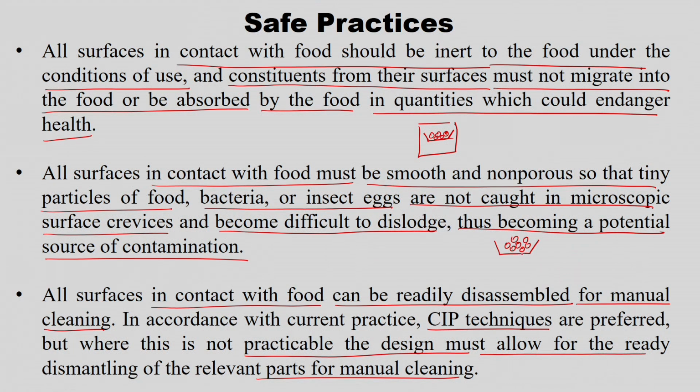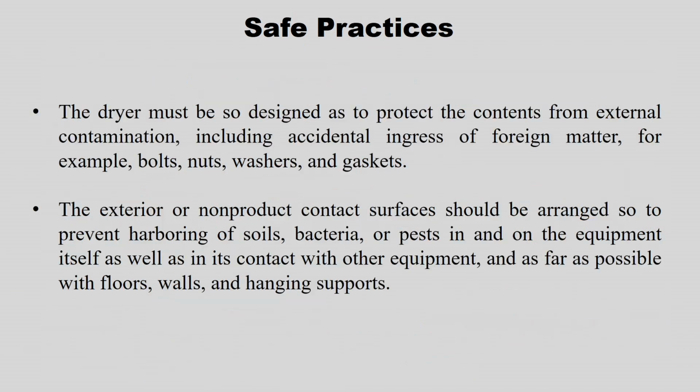So, as we said here, if certain parts need manual cleaning, so we are supposed to give extra care or extra cleaning to certain parts, then the design of the dryer should give the provision to dismantle or disassemble the dryer for extra cleaning. The dryer must be so designed as to protect the contents from external contamination, including accidental ingress of foreign matter, for example, bolts, nuts, washers, gaskets.